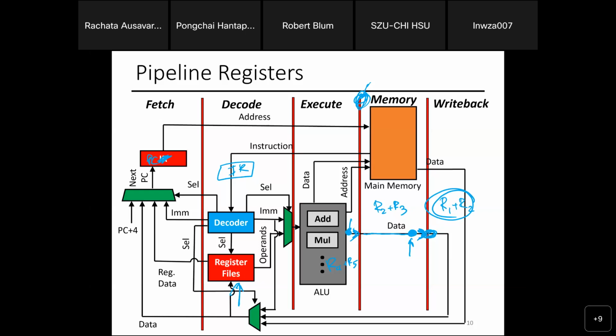And the clock signal is actually another wire that connects all the components. So all the components are built so that they are aware of this clock. Whenever the clock goes to 1, it looks for the time it goes back down to 0 again. And when it goes back down to 0, the hardware updates whatever it has to do that it is buffering right now with the input.